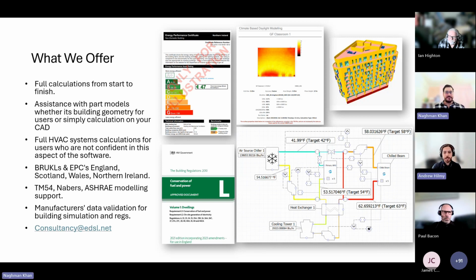Great. And to answer the TM52 report question, we've had TM52 in the software for a very long time now, and it just runs off the dynamic simulation. So you would enter your internal gains properly and run through that, and then you'll get your resultant temperatures out. Then we run through the methodology that is prescribed in the TM52 document, so we use the methodology specified in the document to calculate those results. How you want to include those report findings in an energy assessment is up to you.